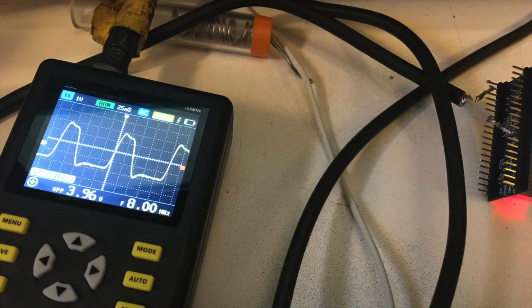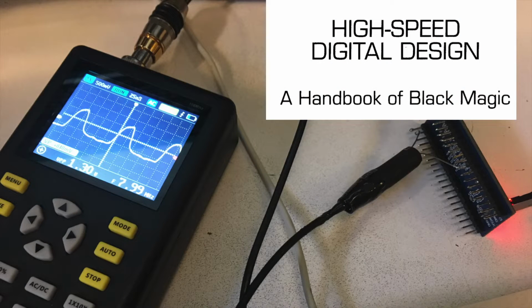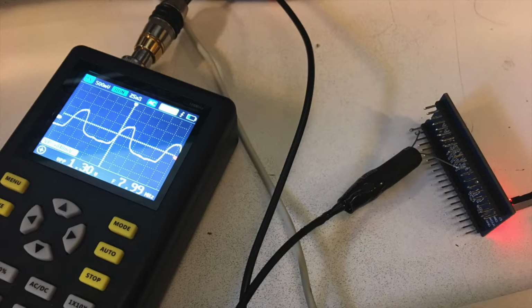And speaking of 50 ohm wire, this is some RG58 that's just soldered right onto it in 1 times mode. This is a DIY probe with a 50 ohm tip on it. The negative goes to the shield, which is RG174 wire. This was based on a passage from the Handbook of Black Magic. That goes to an RCA that has a 50 ohm terminator inside it, and then that's adapted to the BNC connector. So this is what that looks like in 1 times mode. Now, of course, this is going to be a 1-to-2 divider, and there's no capacitive compensation, so this is what we would expect, in addition to the voltages being off.